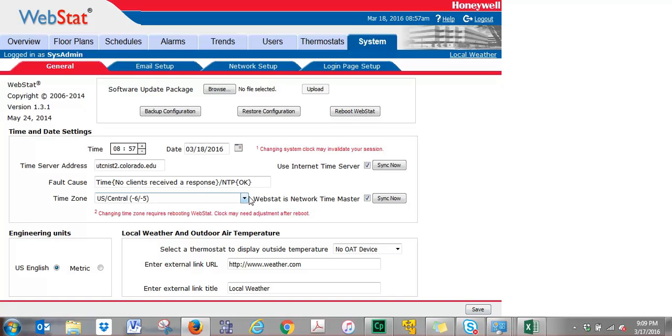All right, if you happen to change your time zone, the problem with that is it's going to make you reboot your Webstat. But just know that that's going to happen if you change that. Now, even though we've added that in there, we've checked these, we still have to hit sync now. So we hit sync now, and it's going to help give us the proper time up top here and the proper date. And once that's done, go ahead and click on sync now to all the thermostats. So once you have the proper time in the Webstat, you hit sync now here, and it's going to make all the thermostats the same time as your Webstat. And with that part done, you're complete.